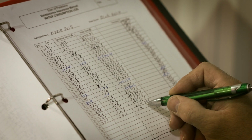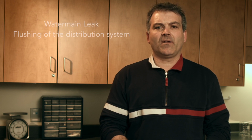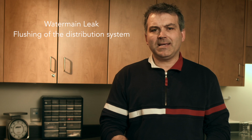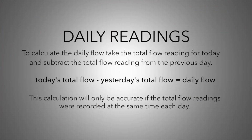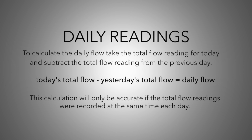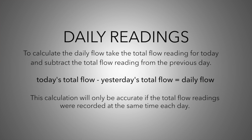Along with the flow data, the operator should also record the date, time, and any issues with the system that may impact the flow, such as a known water main leak or if the distribution system was flushed that day. The operator should also use the total flow readings to calculate the volume of water that flowed through the system on a daily basis. To calculate the daily flow, take the total flow reading for today and subtract the total flow reading from the previous day. This calculation will only be accurate if the total flow readings were recorded at the same time each day.